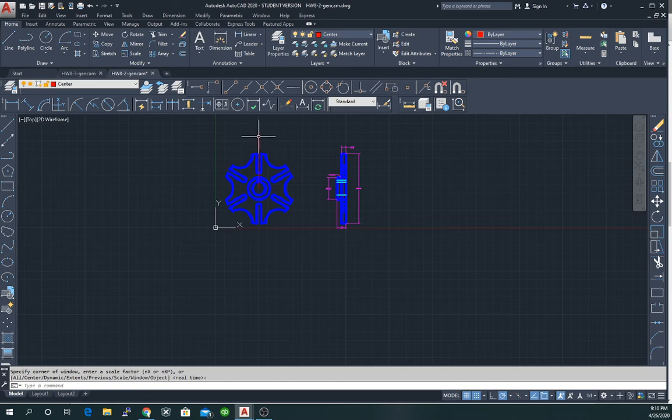And maybe 6.5 is a little long. Delete that. Let's do 5.5. So we'll start here. Go 5.5. And that's pretty good. In fact, we only need to go 5.5 on these two where we had to put in the 60-degree angle marker. The other ones we can just put in a length of 5 and that should be sufficient. Or actually even a length of 4.5. So let's go ahead and put the others in.